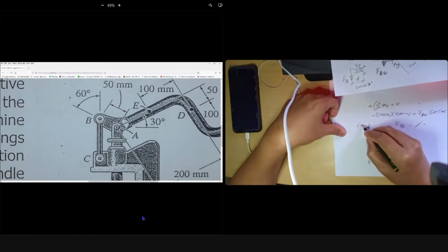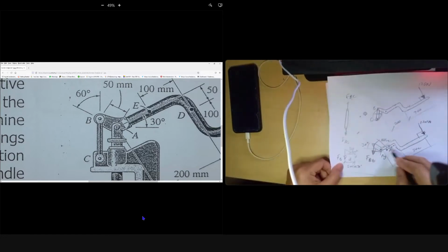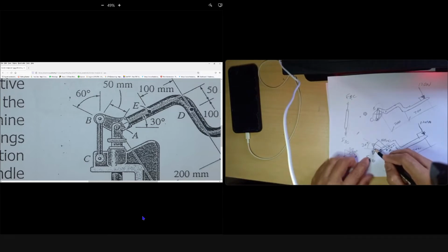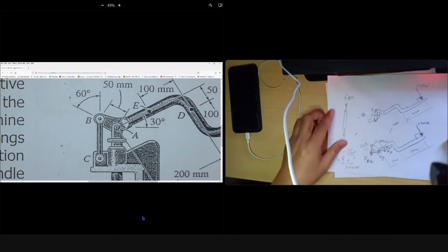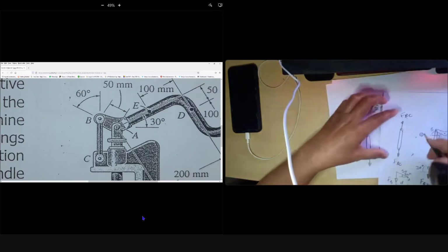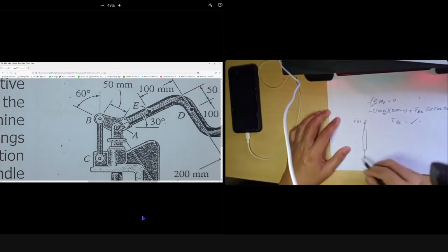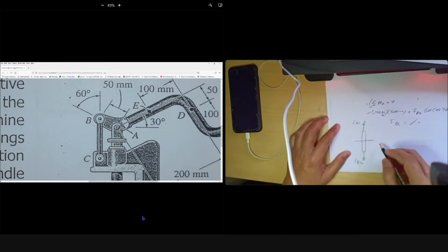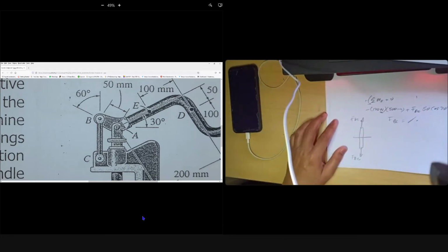Because this is from your handle, in this direction, rod BC is pulling, so it's in tension. The tension goes from FBC to your handle. So it's like this, but your rod FBC must be reversed. It's pulling, so FBC is in tension. Clear? Do you understand, guys? Why is it in tension? Can you explain again how we got 50 cos 30?